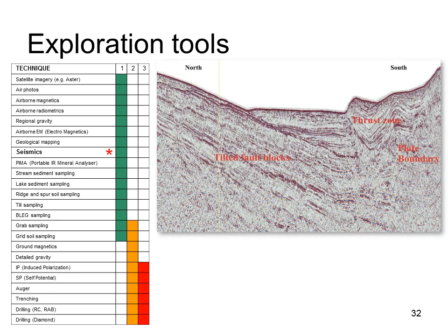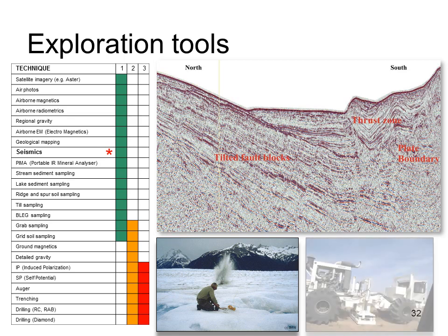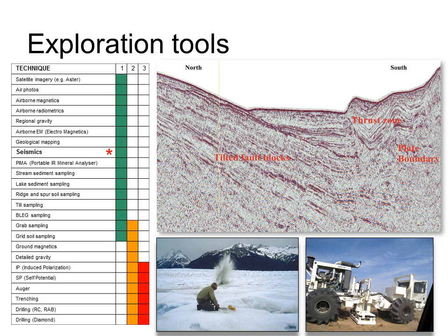Seismic surveys detect variations in seismic velocities in the Earth's crust, and so only work where there's inhomogeneous stratigraphy. The principle is to produce shock waves at the surface, and then measure the echo as the waves are reflected or refracted off rock boundaries at depth. The initial shock waves are created by explosives or vibration using big trucks that repeatedly drop weights, or simply vibrate large pads in contact with the ground.